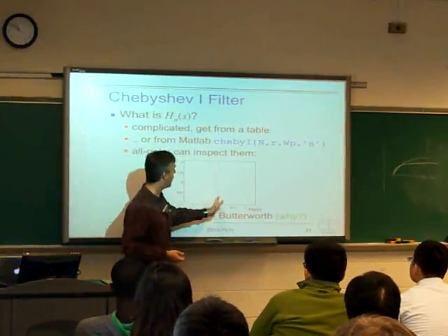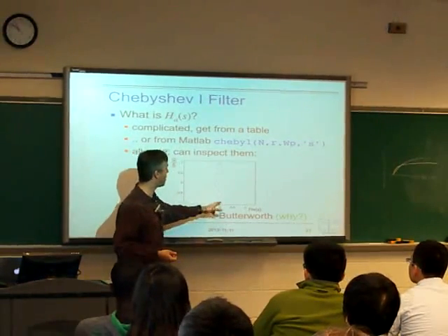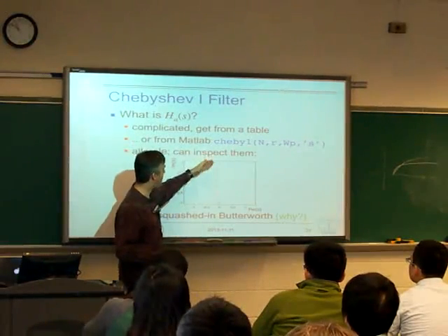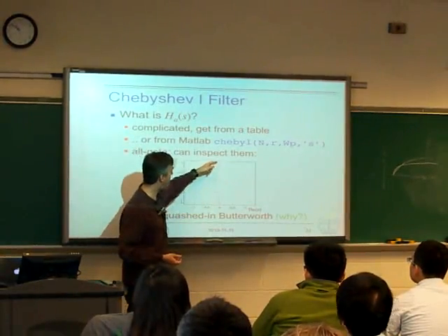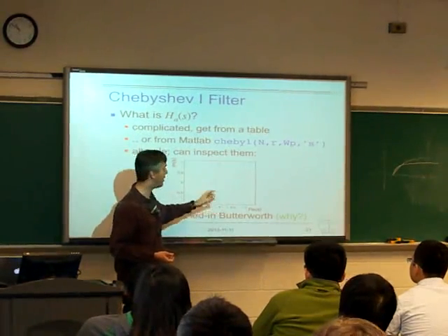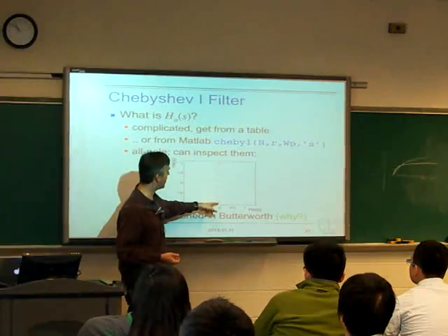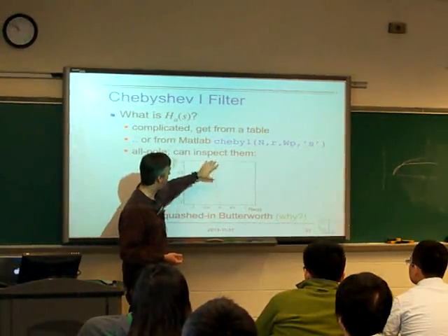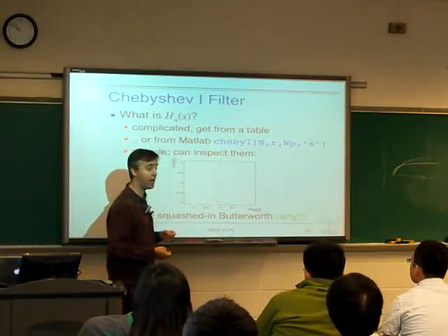Remember, for the Butterworth filter, we had these poles on a semicircle. For the Chebyshev filter, they're the same poles, but now the real part has been scaled in. So if we stretch them out to touch the circle, they would be uniformly spaced around the circle. When we scale in the real part, they end up being more bunched up towards the 3 dB frequencies here, and they're obviously much closer to the j omega axis.